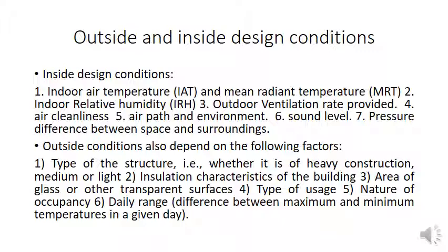Then the insulation characteristic of the building, whether the single stage insulation means only internal or external insulation is provided, or some insulation is also provided between the two consecutive walls. Then the area of the glass and other transparent surfaces, whether the glass is tinted, painted, opaque or transparent glass, as it may also be part of the outside design condition.